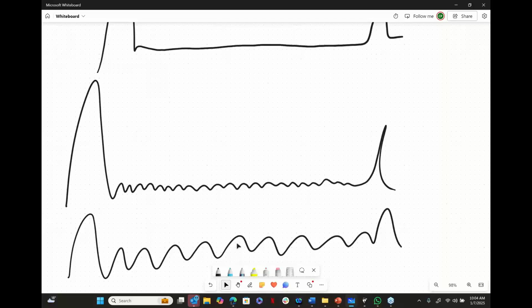It could be that your vertical gain is just too high, because the question that I'm going to ask you is, on this line or on this line, does anything stand out from the rest of the line? And it doesn't. It's entirely possible that this line and this line and this line are all exactly the same, just with the vertical gain turned up too high.